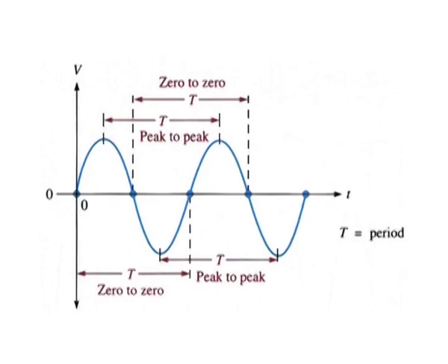There are three possible ways to measure the period of a sine wave. Method 1: the period can be measured from one zero crossing to the corresponding zero crossing in the next cycle. The slope must be the same as the corresponding zero crossings.